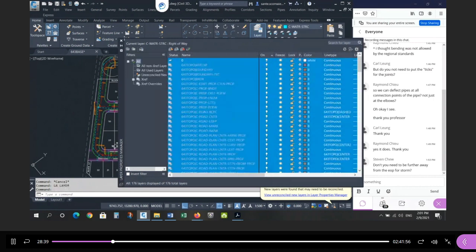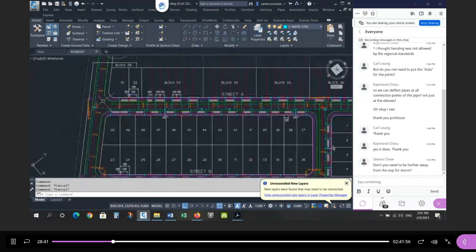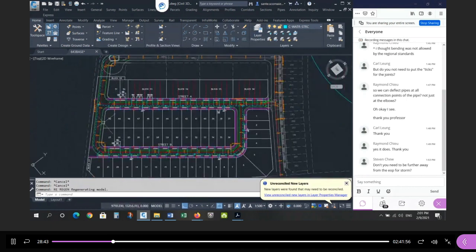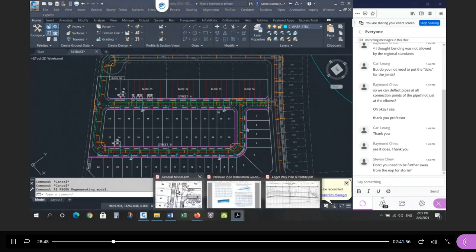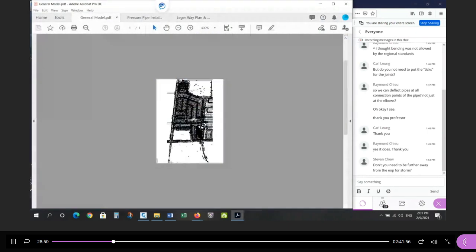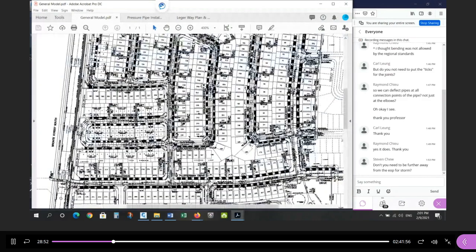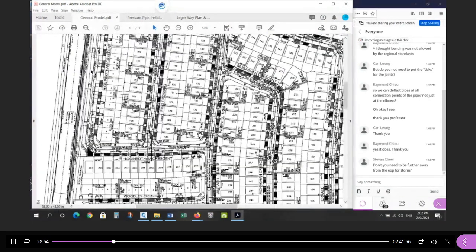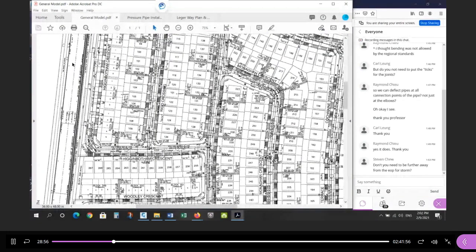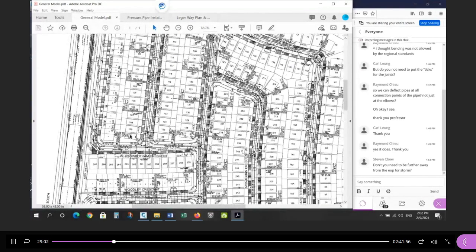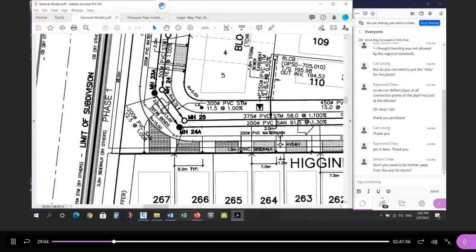Okay, so let me just turn on a few more layers here. All right, the other thing is there's no sidewalk required here. Okay, and I'm going under this assumption. Any road, the window roads, the roads that have only houses on one side and are adjacent to the road exterior to the site, any of those connections in the elbows has the sidewalk go outside the subdivision at this point here and connect to this existing 3-meter wide sidewalk.